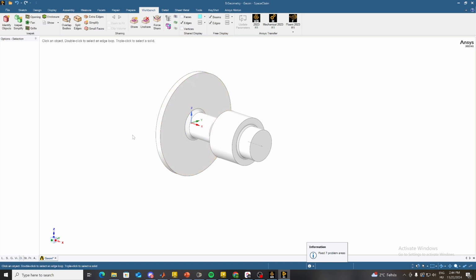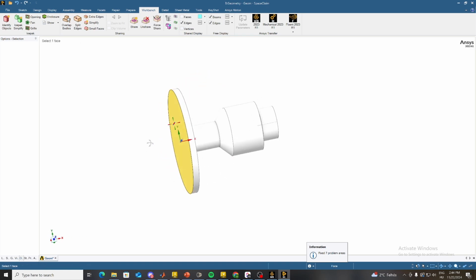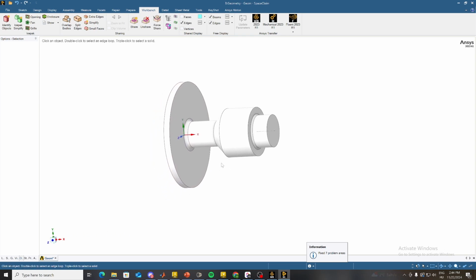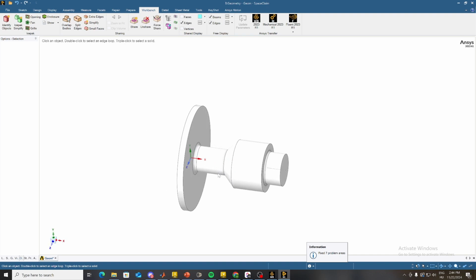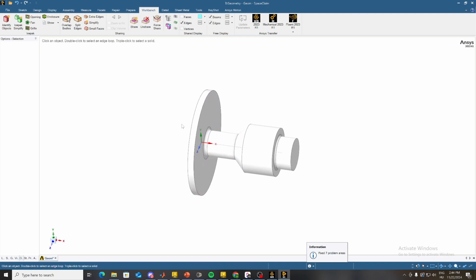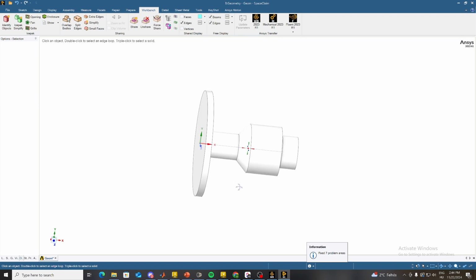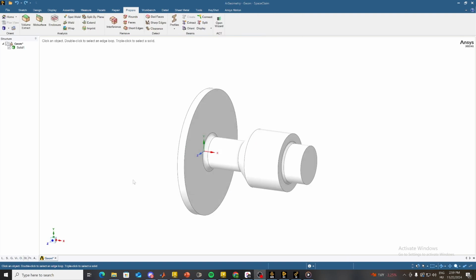Ansys structural can only handle this 2D axisymmetric problem if there are no nodes containing smaller y-axis values than 0. So they must be positive. This is true on the x-axis too.